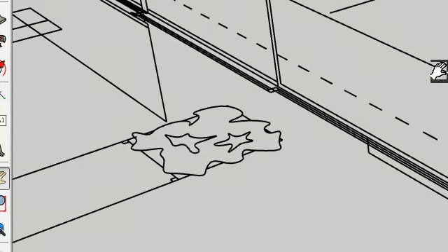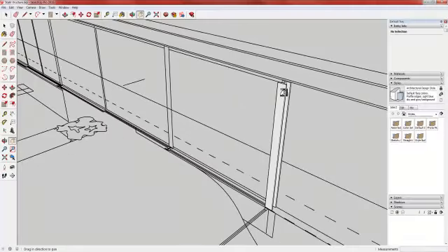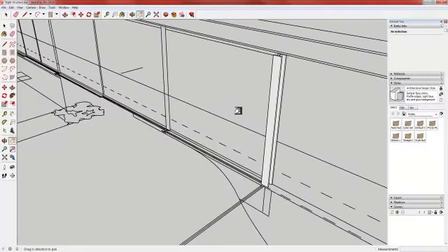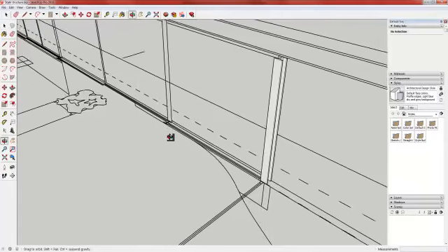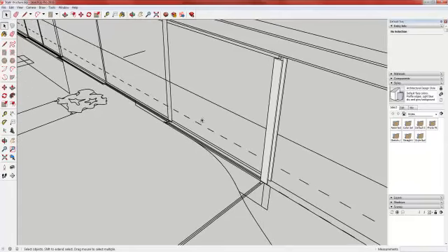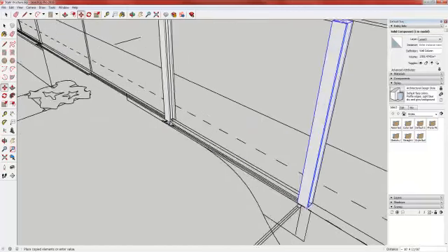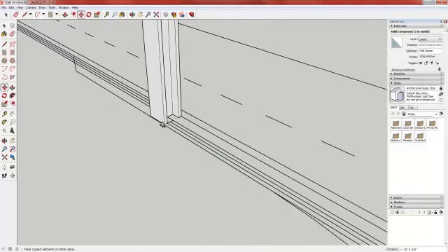Now, typically, in structural plans, we have repetitive columns, especially commercial buildings, and we try and place those columns on what we call a column grid. And it makes a lot of sense structurally to have the column grid be equal spacing. We're going to see how close the Stahl house or these drawings actually do that. So I'm going to select our column. I'm going to make a copy of it. I'm going to select Move, and by holding down the Control key, I'm going to just move the column over to the next column location, and it fits really nicely.